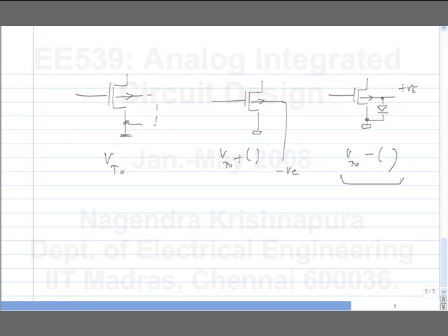Now, because the threshold voltage is reduced, the VGS for a given current is also smaller. So you can in fact tie this here and use it in some applications. But you have to make sure that this voltage will not be more than about 0.2, 0.3 is probably maximum. Beyond that, it will start conducting substantially. So we are to some extent lowering the input impedance also.